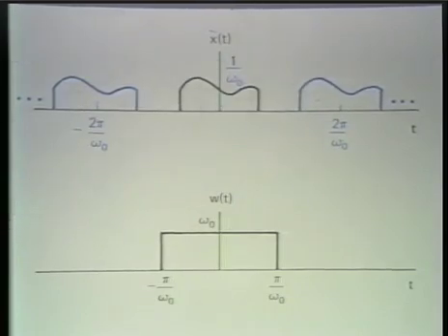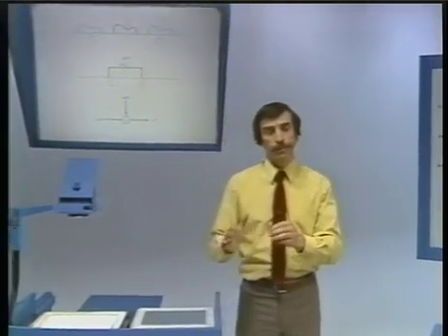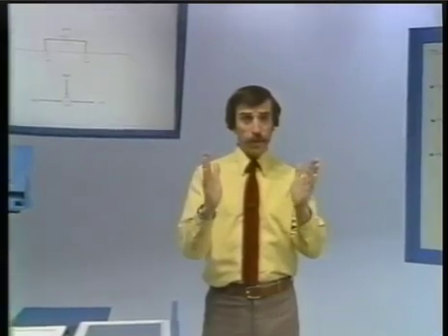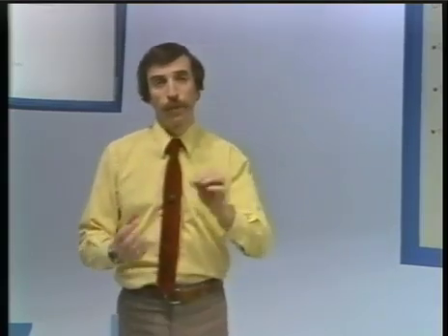And so what this means is that if the sample spacing in frequency is not small enough, we can end up with an overlap in the replication in the time domain, and what that corresponds to, and what it's called, is time aliasing. So we can have time aliasing with frequency domain sampling just as we can have frequency aliasing with time domain sampling.